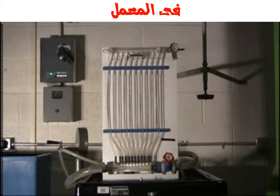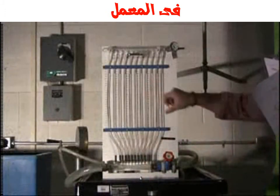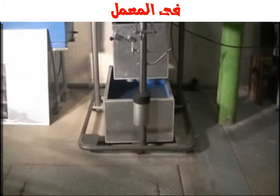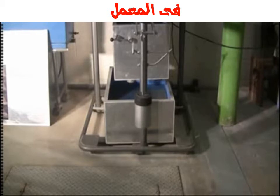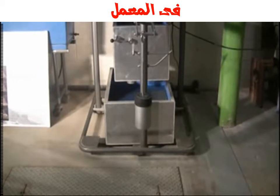Now make sure that there's no air trapped in the piezometers. If so, gently tap them in order to remove the air bubbles to the top. Ensure that a weight of 9 kilograms is attached to the free end of the lever arm. This should comprise the 7 kilogram silver weight and hook and an additional 2 kilogram free weight. Make sure that the weight measuring tank is unplugged by keeping the lever on the front of the tank in the horizontal position.